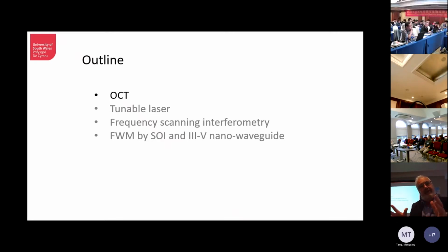The technology is moving on in metrology in the real world, and people are migrating from a fixed wavelength laser to a frequency tuned laser, where you change the wavelength. Now in an interferometer, like a Michelson, when you've got a tuned laser, you start generating what we call beat frequencies. Depending on the chirp rate of the laser, those beat frequencies dictate what the distance is. So you've got a different means of measuring the distance. Within that embodies a lot of new technology, which we need to work through to find traceable standards. And there are problems.